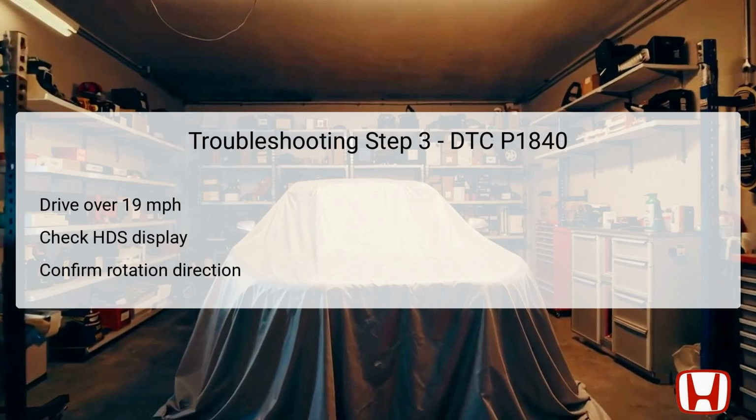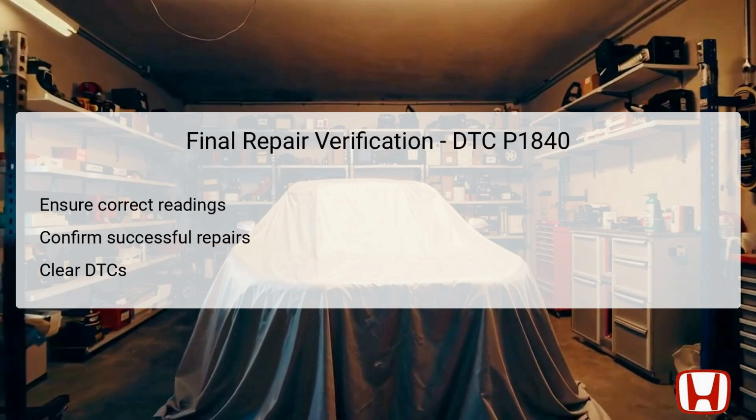Nonetheless, if the reading appears normal, this provides insight into the health of the TCM and other components in the system. This step plays a pivotal role in determining whether the issue lies with the CVT speed sensor or the TCM. After completing necessary repairs, conducting a final verification is paramount. This process involves ensuring that the readings from the HDS conform to the expected outputs, especially that the direction of secondary shaft rotation displays forward.